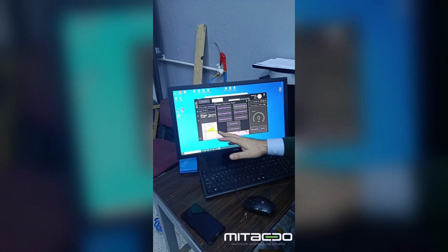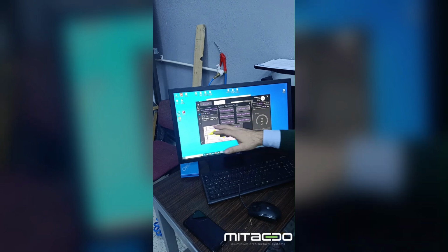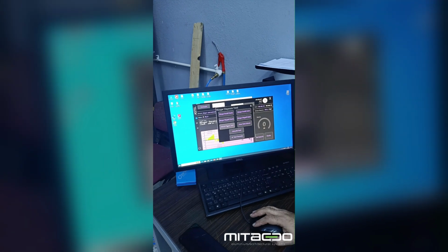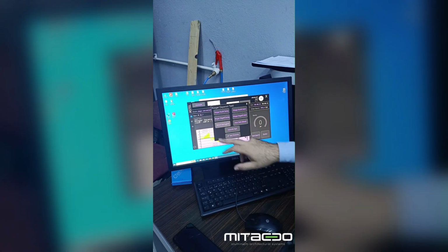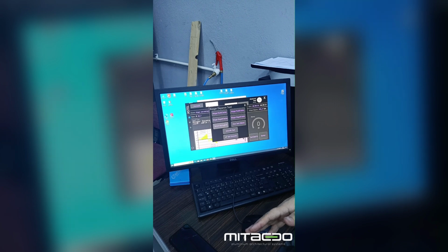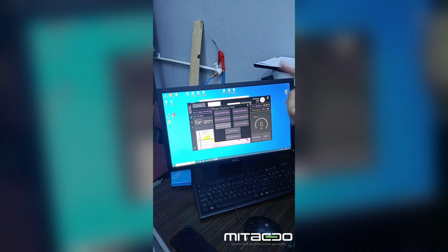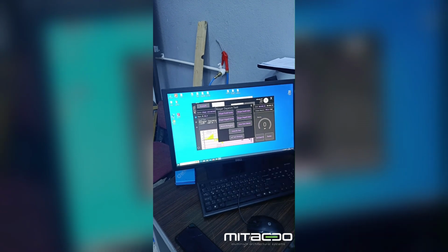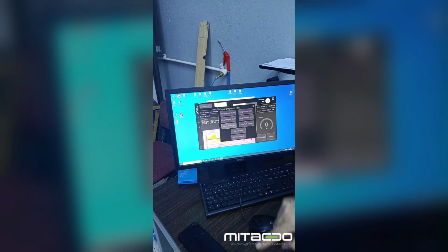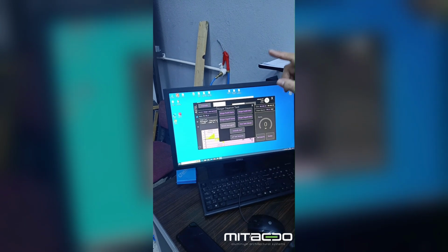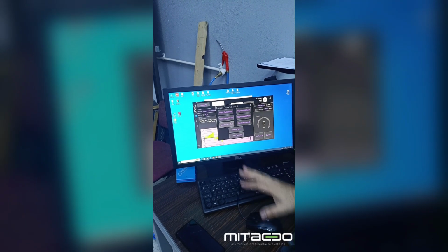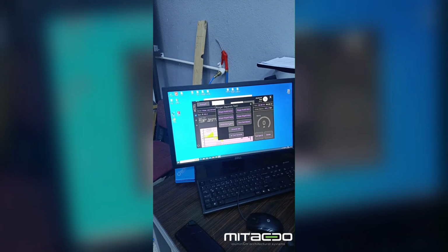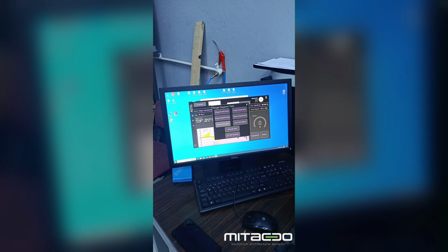We have now completed the positive and negative wind test and deflection test. We will begin repeated pressure testing. In this test, we will go down to minus 800 pascals and go up to plus 800 pascals. In this way we will repeat this cycle 50 times. So it's always minus 800, plus 800, minus 800, plus 800. It's going to come and go. He will have done this in 50 cycles. It will wait 7 seconds in between when it goes down to minus 800 and goes up to plus 800. So it's a pretty fast, dynamic test.